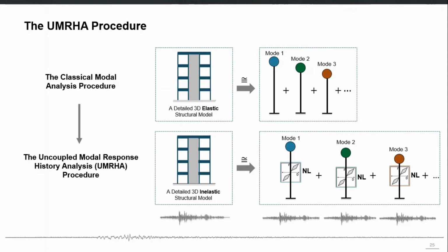The classical modal analysis procedure says that you have an elastic structural model, a multiple degree of freedom system. You can approximately decompose its response into the response of the first few vibration modes, and each mode is represented by a single degree of freedom system mathematically.